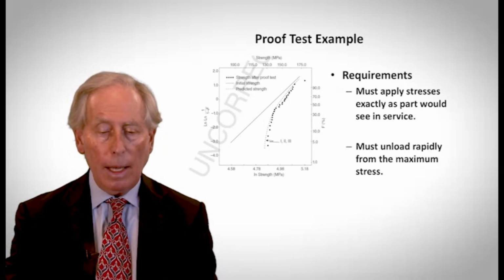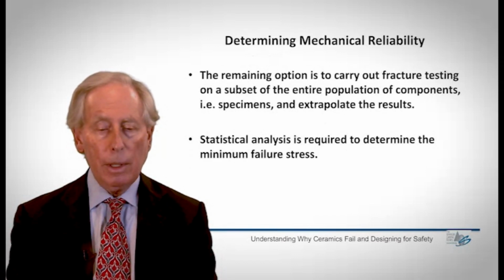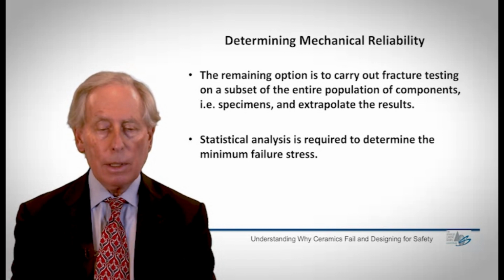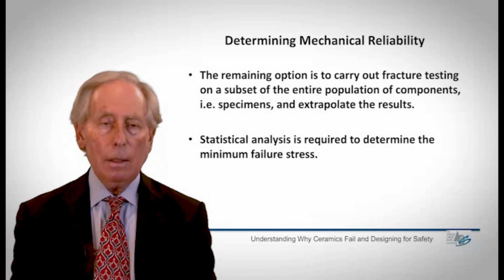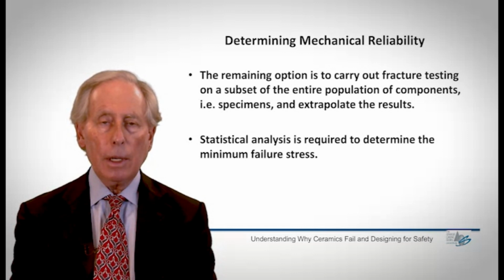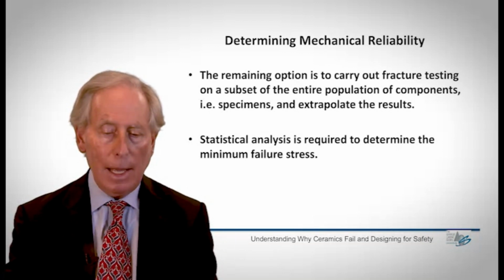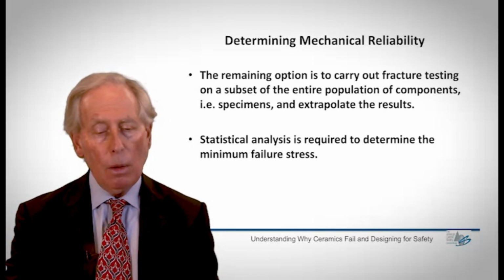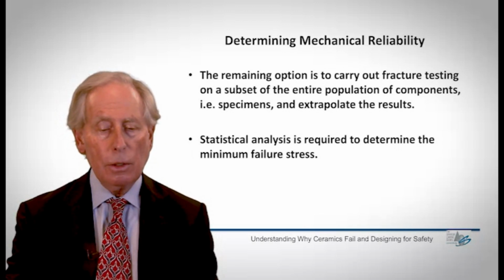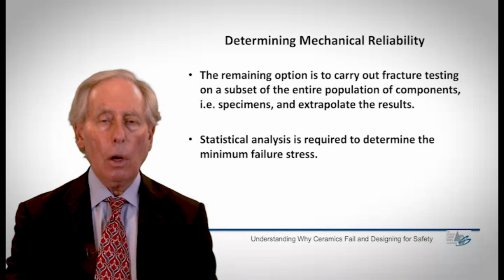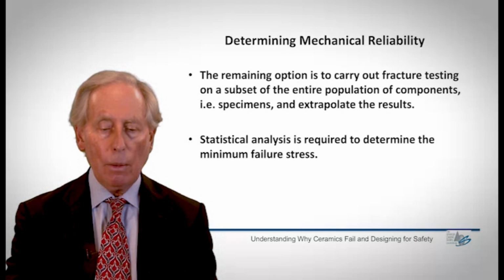So we're left with one third option, and that is to carry out fracture testing on a subset of the entire population of components, namely specimens, and then somehow extrapolate what we learn from that set of specimens to predict what happens in the components themselves. And that's the theme of the rest of the presentation in this section. So that requires a statistical analysis to determine what will be the minimum failure stress we should expect in a large number of components that we might want to produce.